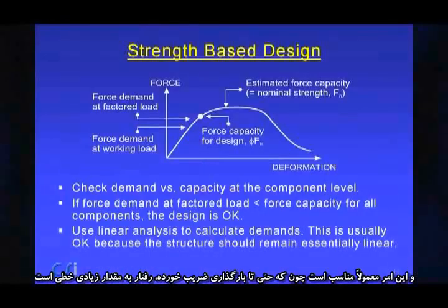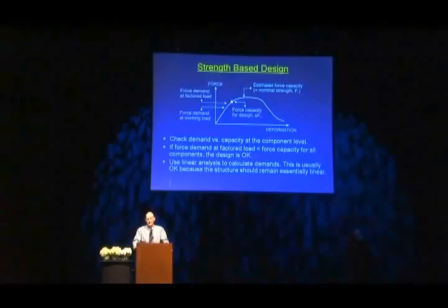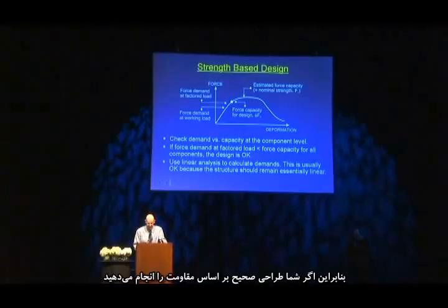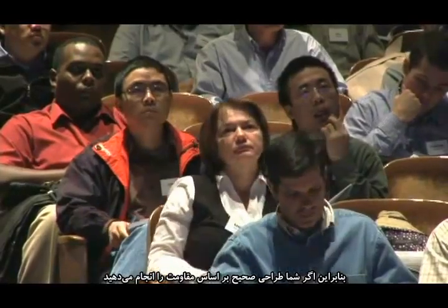What you do here is you can use linear analysis to calculate the demands, and this is usually okay because even up to the factored load, the behavior is pretty much linear. So if you're doing true strength-based design, you can use linear analysis.